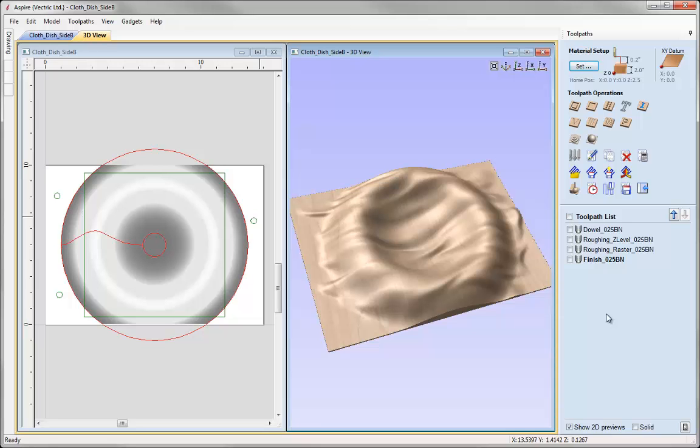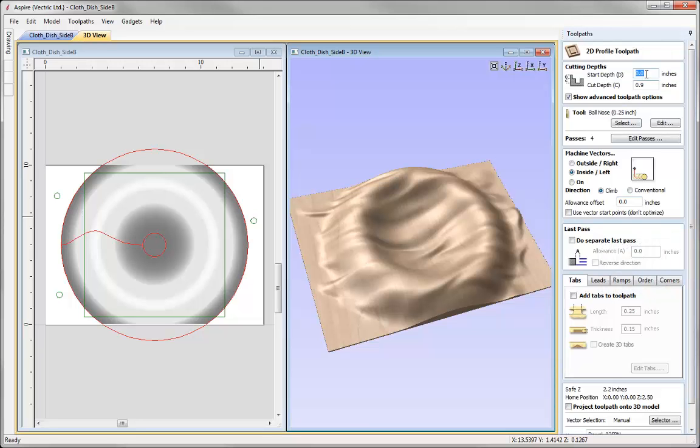or maybe something that you've clamped on it for this purpose. So we're going to take the same toolpath, if we double click on it, but the start depth this time is going to be 2 inches. As I say, we're imagining there's no piece of material on here, and the cut depth only needs to be enough to make sure that there's enough clearance for our dowel to go into, however much of the dowel is protruding when we flip the part over.